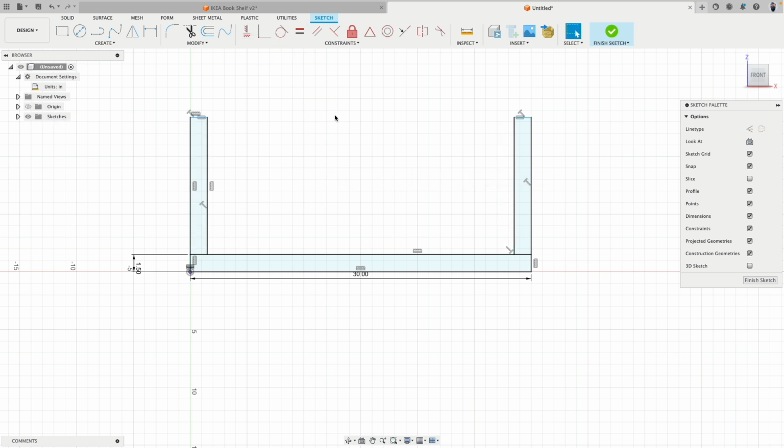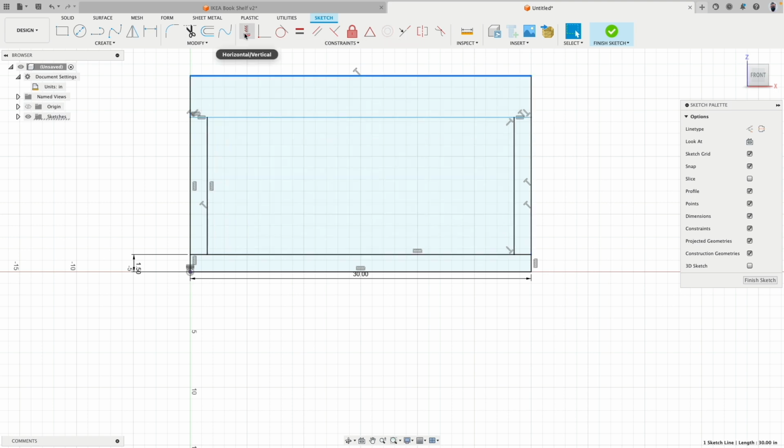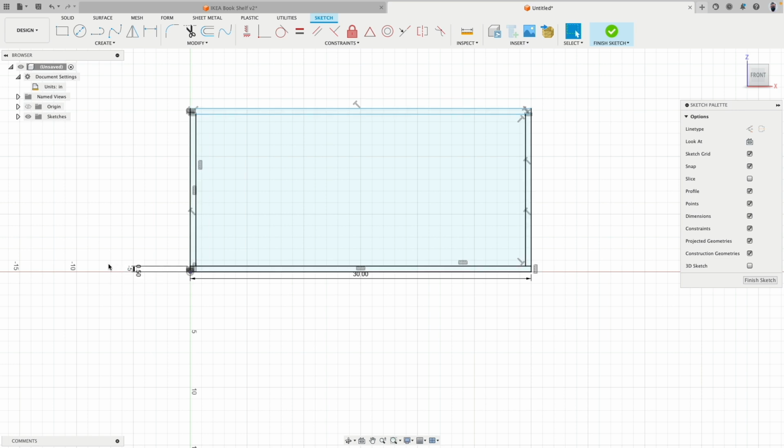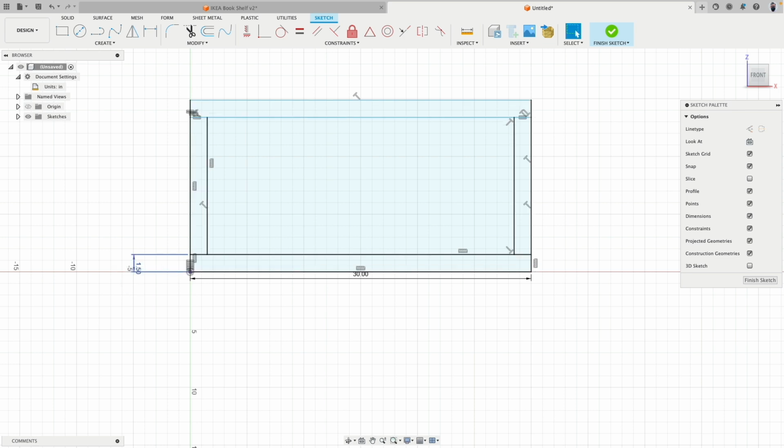Perfect. We have another piece that goes over, so I will draw one line to there and then one line up, over and down. This creates automatic perpendicular constraints. If you don't see this, then select the edges and set them horizontal, vertical. And here, this edge and this edge I make equal too. Again, little demo, 0.5. You see how this updates. So this is actually a sketch-driven design, as you will see later.